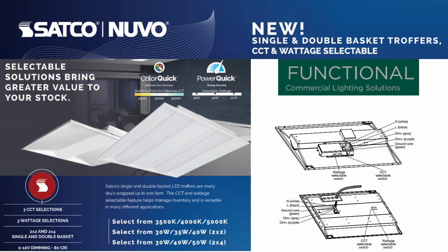For basketed lay-in, we have both single and double basket troffers or lay-ins. They feature Color Quick and Power Quick. 3 color temperatures selectable, 3500, 4000, and 5000, and Power Quick allows you to change the wattage from 30 watts, 40 watts, or 50 watts.